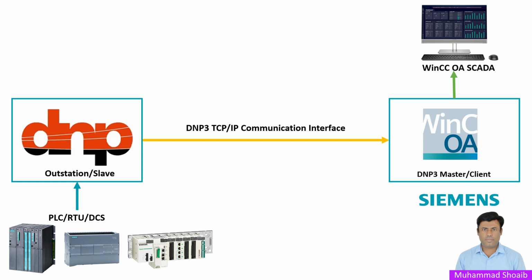And using the DNP3 protocol, we can synchronize our RTU time with the master SCADA. DNP3 is a secure network and it uses secure authentication. And the DNP3 protocol can support serial or TCP communication also. In this tutorial, we will learn how we can configure the TCP communication.